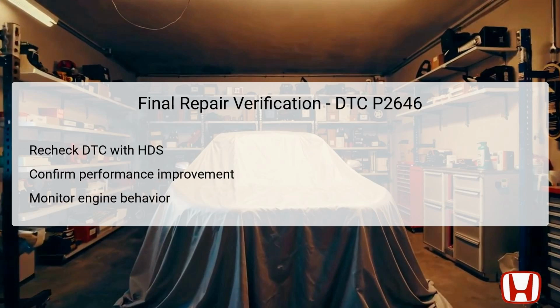Upon completing the necessary repairs or replacements, it is imperative to verify the effectiveness of the service performed. Reconnect the diagnostic tools and use the Honda Diagnostic System to recheck for the presence of DTC P2646 or any related codes. A successful repair would show no DTCs and a clear history of proper performance from the rocker arm oil pressure switch and VTEC system.